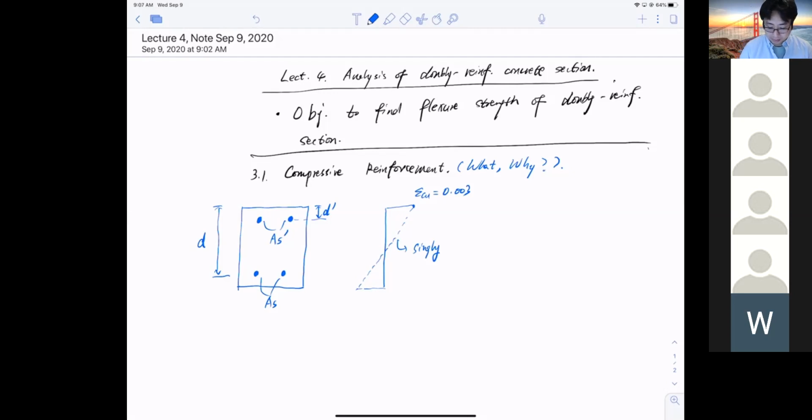It'll increase. Think again, compressive reinforcement. It should increase because it's taking more to compress it. Wait, think about it. I now have steel added to take care of part of the compression together with the concrete. So instead of just the concrete taking care of the compression, you have steel to help it. Do you need more concrete or less concrete? Oh, I misunderstood. You'll need less concrete. Right, you need less concrete.